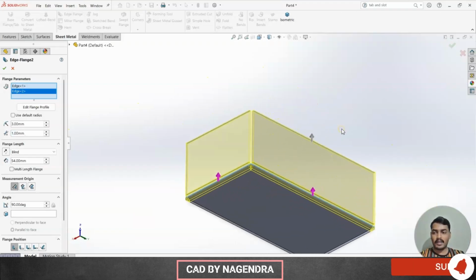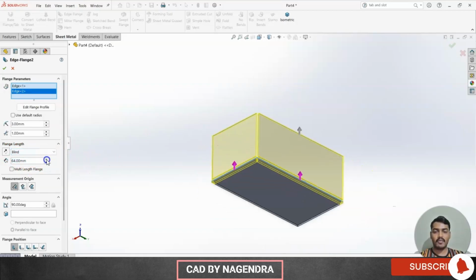Then next we have flange length. Blind means our own dimension. Then up to vertex means if we have any proper separate point, and we want to make this edge flange up to that point, we can select up to vertex. Now we will go for blind only. How much height we want, we can change.